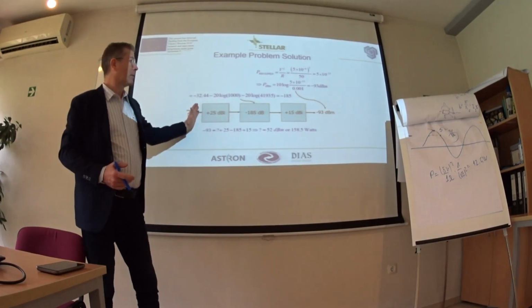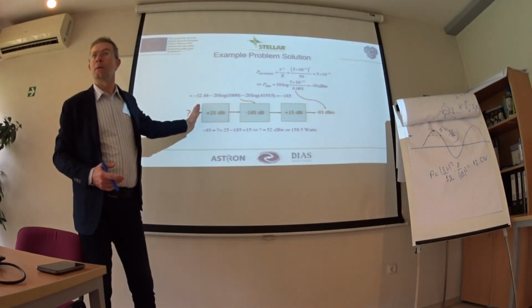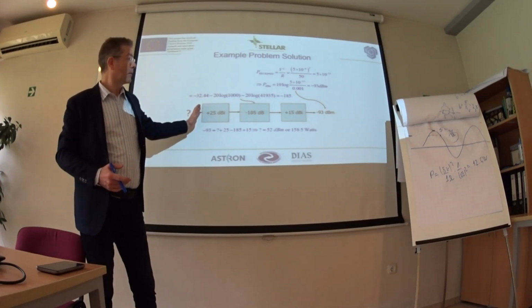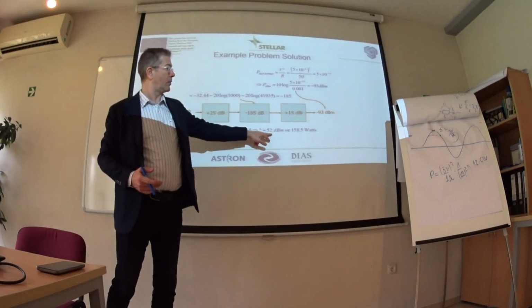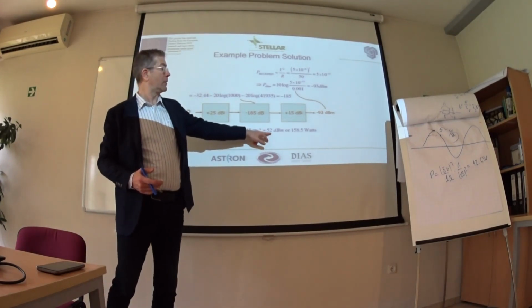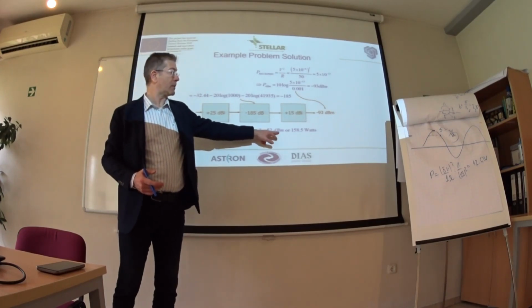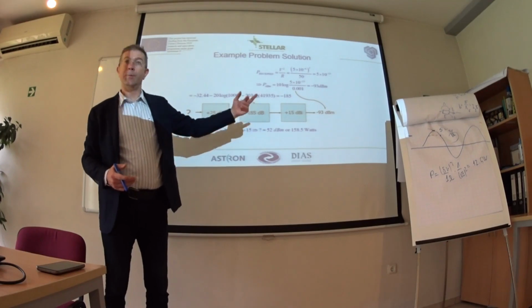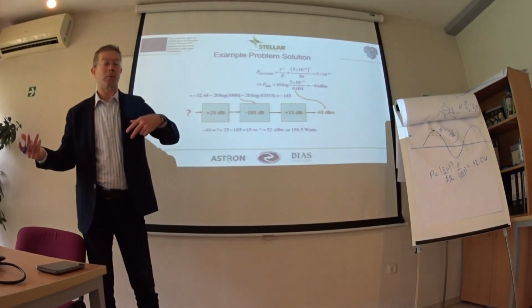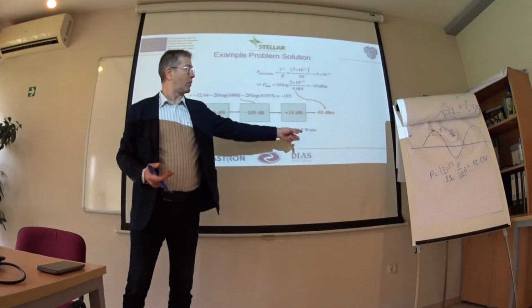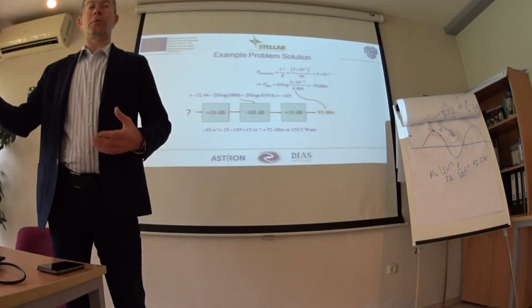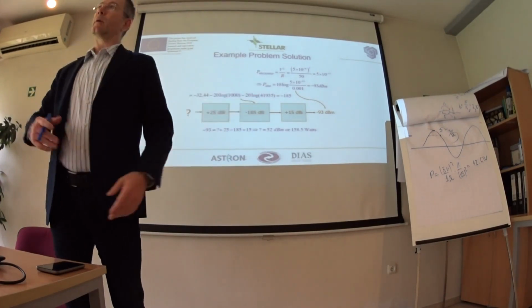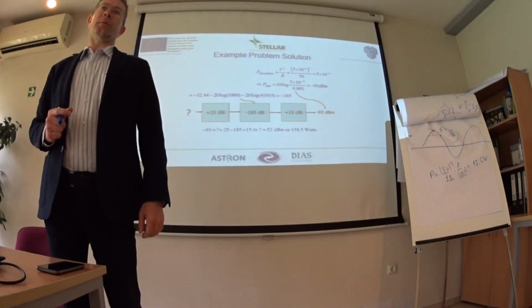And then we add the gain of the transmitter antenna. Assuming all these numbers, we get plus 52 dBm, which is 32 dBW, and once we convert it to watts, we get 158 watts we have to transmit in order to get this small power on geostationary orbit.